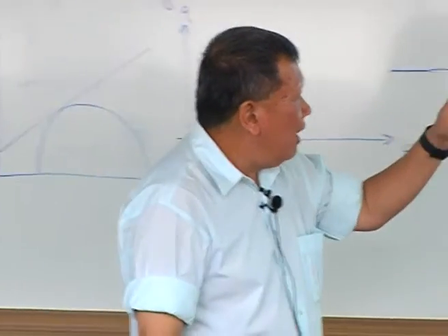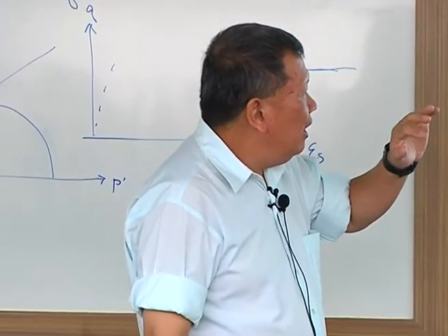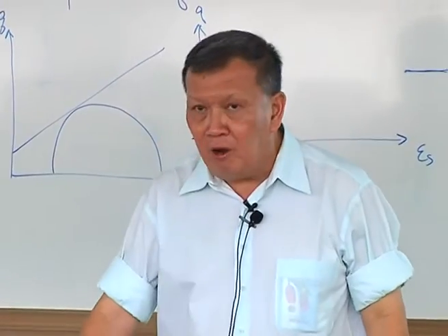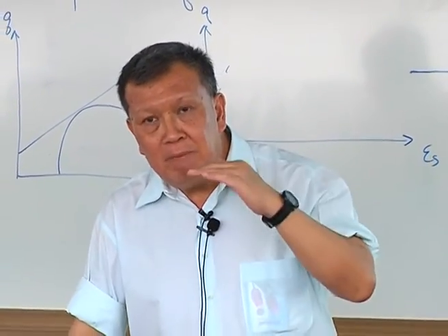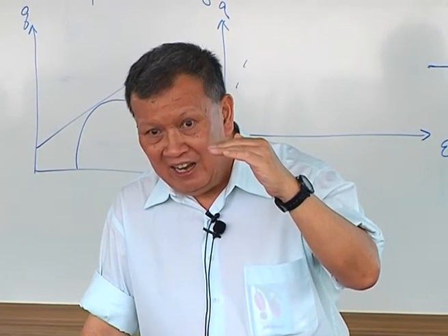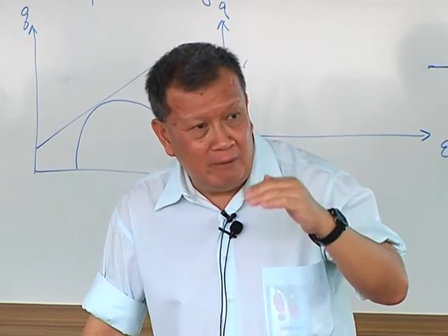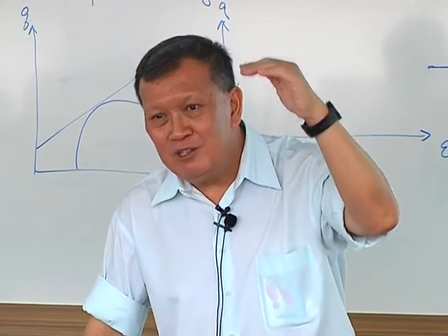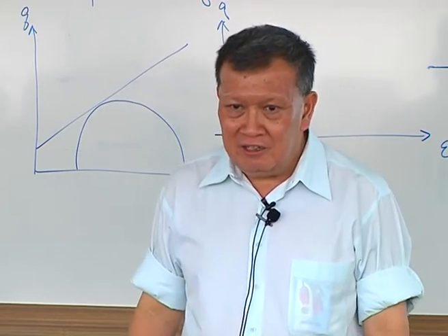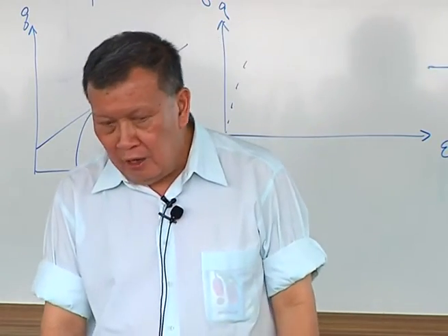And that is the reason why you find that the ellipse, because you remember I told you that the modified Cam-clay typically predicts a K0 that is higher than Jaky's. Right? So Plaxis tries to correct for that by pushing up the ellipse so that it gives you back the Jaky's K0 value.